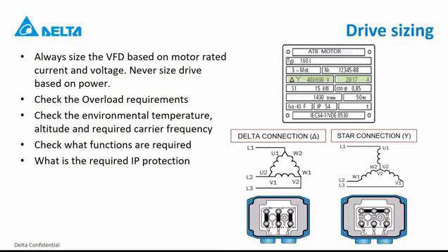In most cases, you install drives in some electrical cabinet, and in those cases, IP20 is okay. But in some cases, some installations will install the drives very close to the motor, and in those cases, you need around IP55, and you can use the CFP2000 drive.